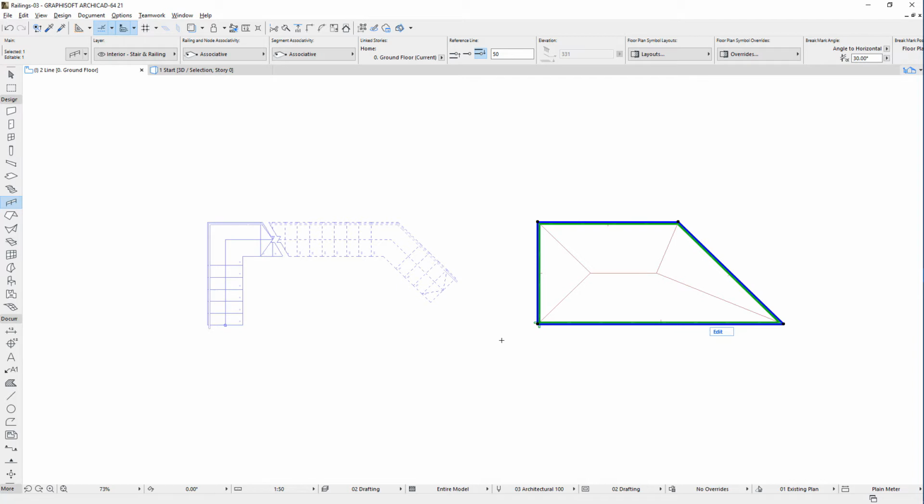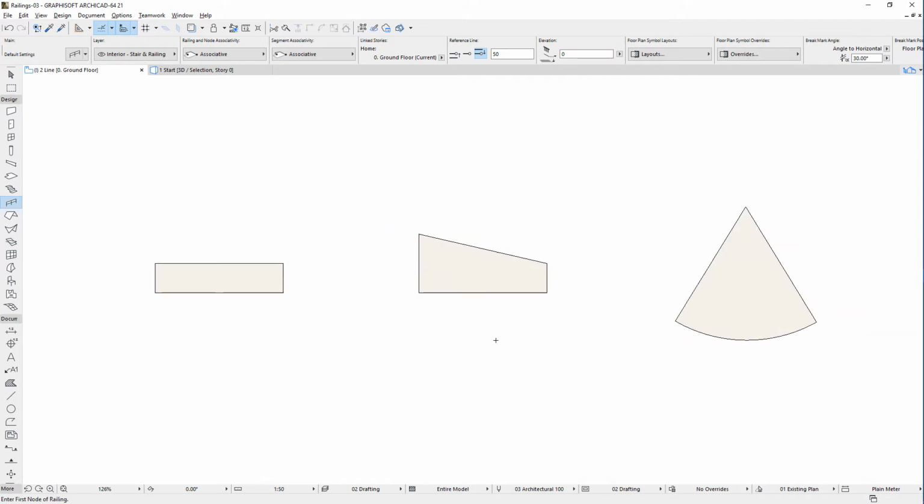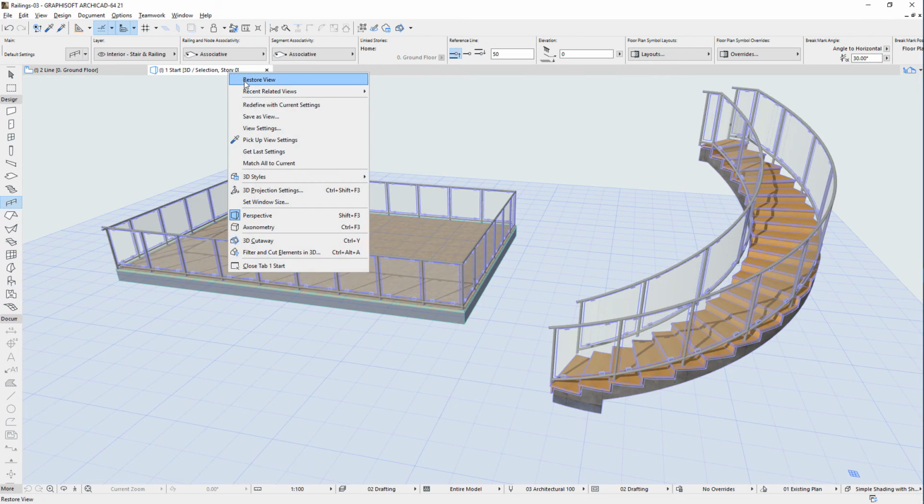the space-clicked point. You may also space-click within the body of a straight, trapezoid, or polygonal wall. The railing in this case will be generated just like in the case of closed polygons, and the created railing starting node and end node will both be located at the node of the wall polygon closest to the space-clicked point. You can use the Magic Wand in the 3D viewpoint as well.